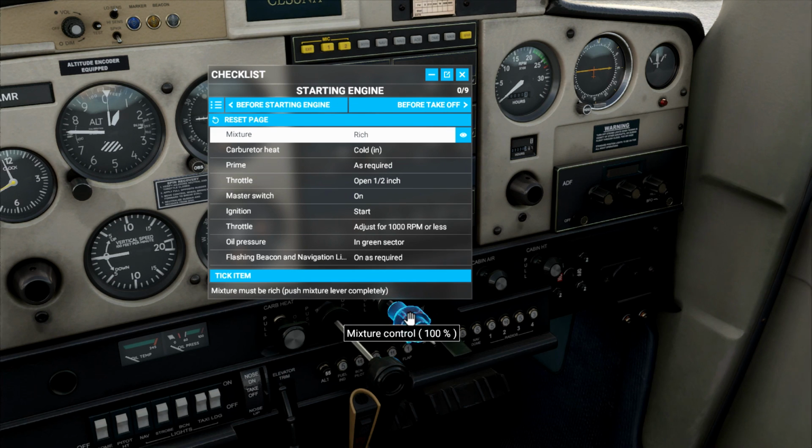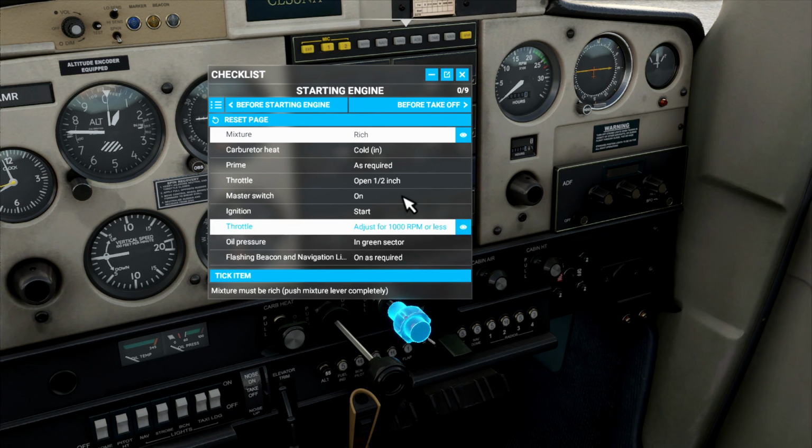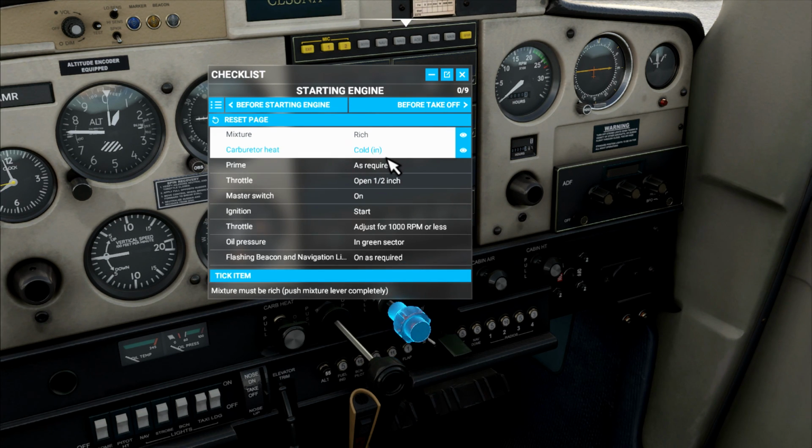At ground level here, we're at the maximum air pressure that we'll have during our flight unless we plan to fly into an area whose altitude is lower than the airfield. As we gain altitude, the air pressure lowers and the PIC will need to adjust the mixture during the flight in order to maintain RPM and power in the engine. One of the benefits of altitude, besides giving you time to make decisions and aviate before you hit the ground, is that you'll use less fuel. You generally account for this in your flight plan.